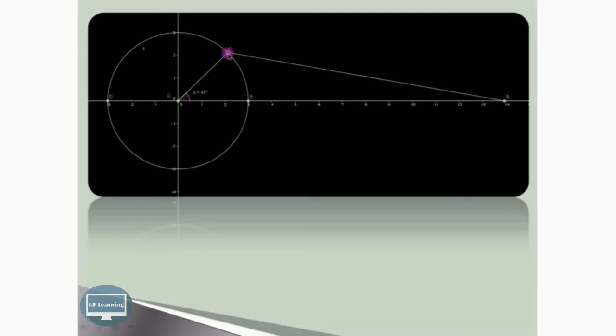So there are two types of acceleration. One is radial or centripetal acceleration and another one is tangential acceleration. Now as the crank rotates uniformly, the tangential acceleration will be zero. So this crank will have only radial acceleration. And we know that radial or centripetal acceleration is always directed towards the center. So O is the center. So here the radial acceleration of A with respect to O will be directed towards the center.